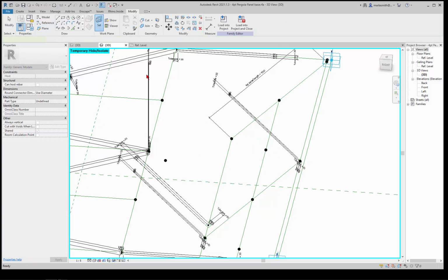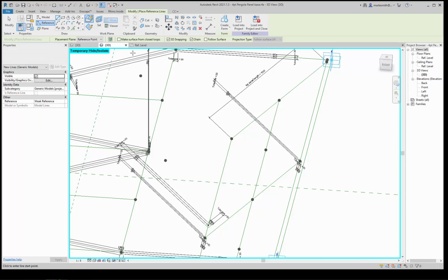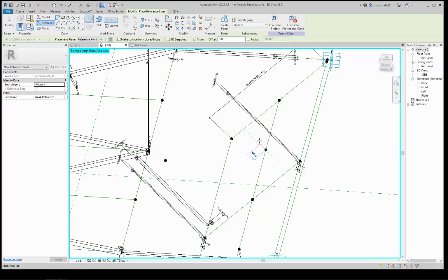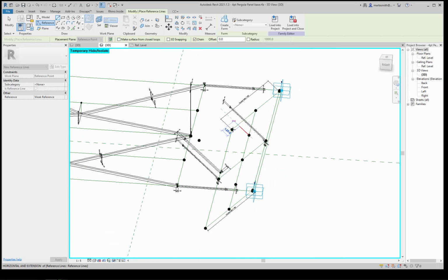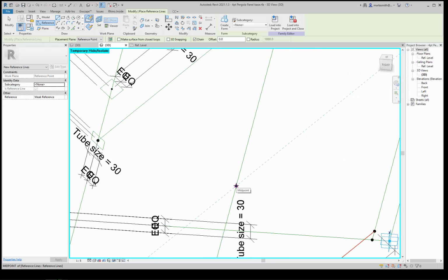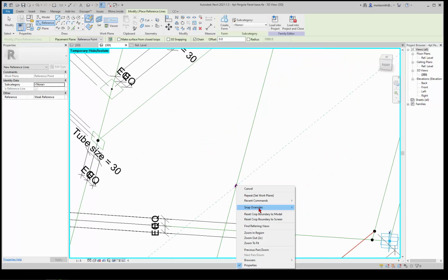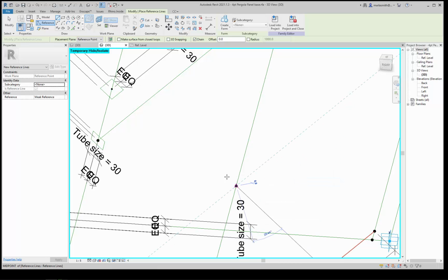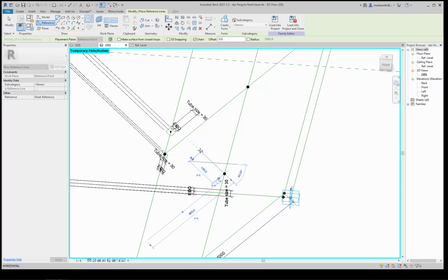I'm going to set this current, and I'm going to make the working plane current and get rid of 3D snapping. And the only thing you have to make sure of is that if it were at 0, that it would be flat, right? So if I draw, or this one we actually want to go vertical, so this one would go up this way, right? And then if I set this one, sometimes it wants to do endpoints, and I always like to get the actual point, so sometimes I snap override and do points. Most of the time it's not a problem, but sometimes Revit's a pain in the butt sometimes.